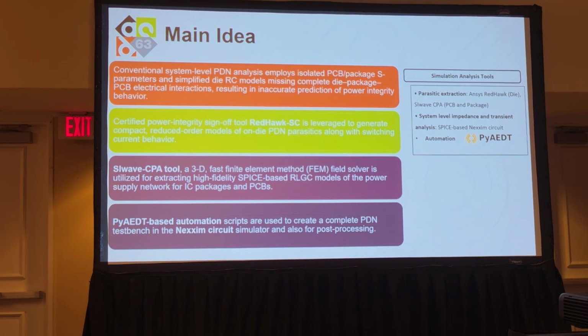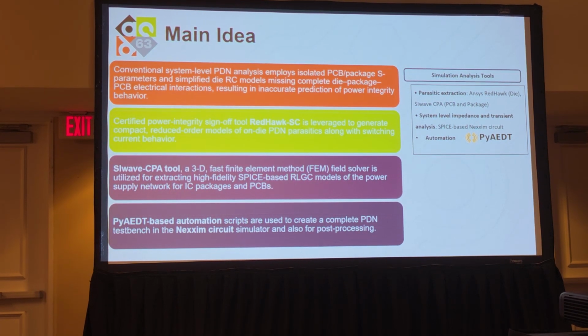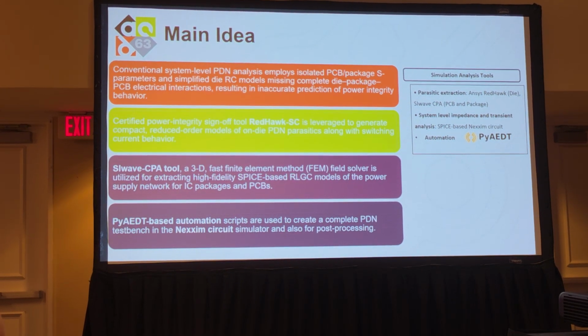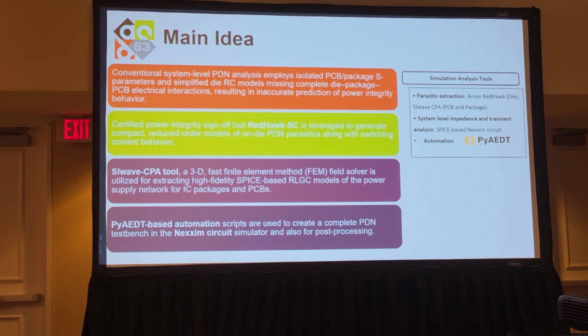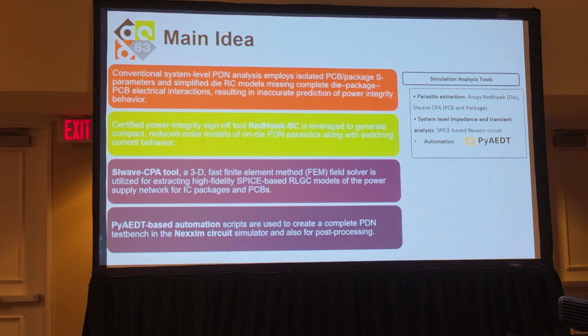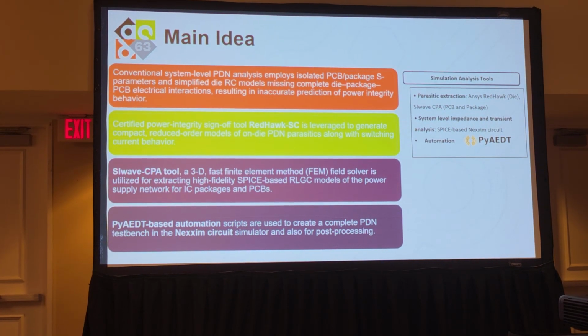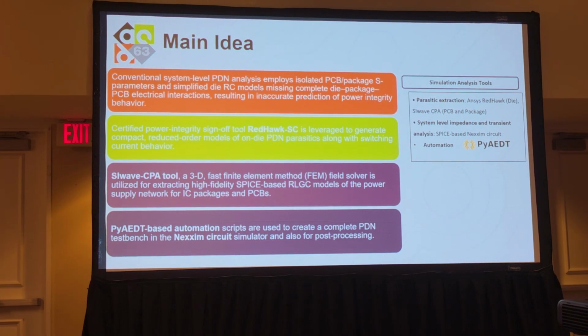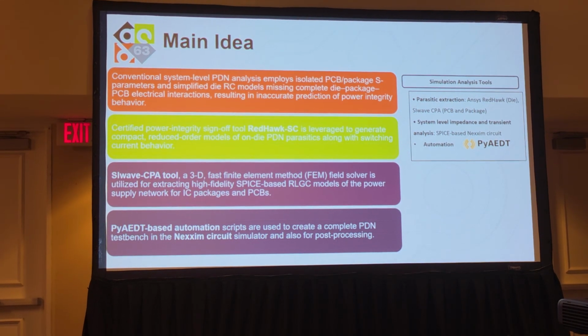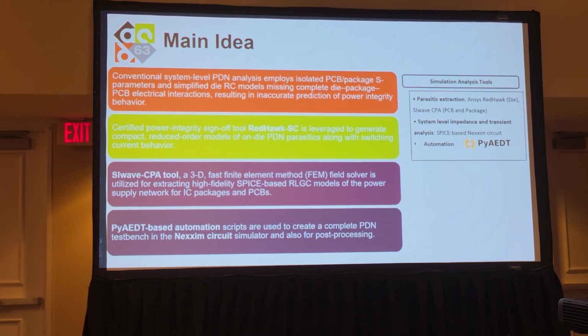So, again, the idea is if we can accurately model everything in an efficient way, we can do a better design. What we've previously done in the past is a split and stitch method. In other words, we have characterized each particular device, the IC, package, and circuit board individually, created S-parameter models for them, which we stitch together.